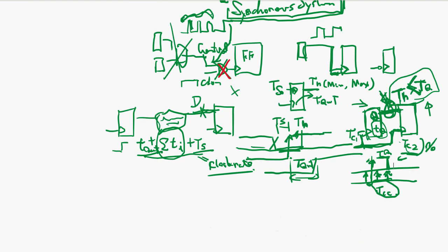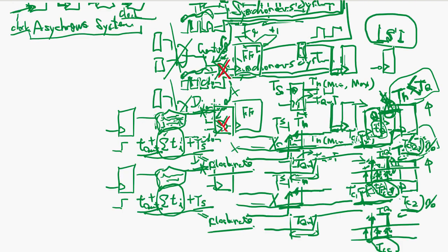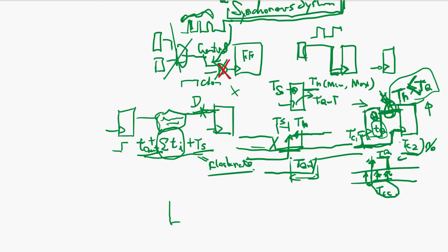this happens when a clock signal is driving many flip-flops, right? Then it doesn't become a nice rise time. Sometimes it becomes this kind of clock. Then you have all kinds of problems, because where you measure setup time and hold time is usually from the center, right?